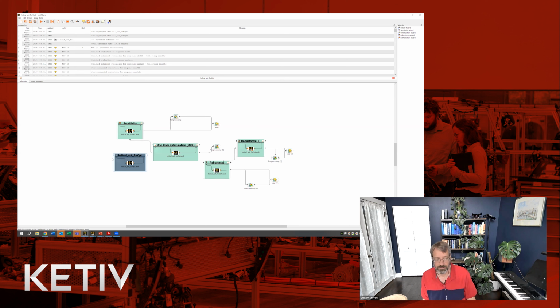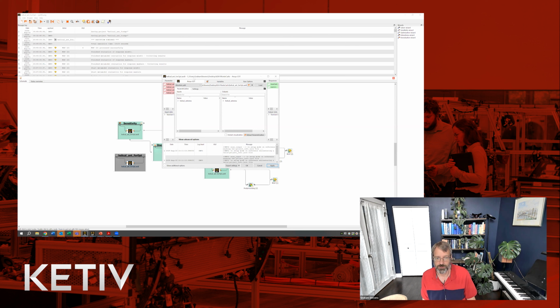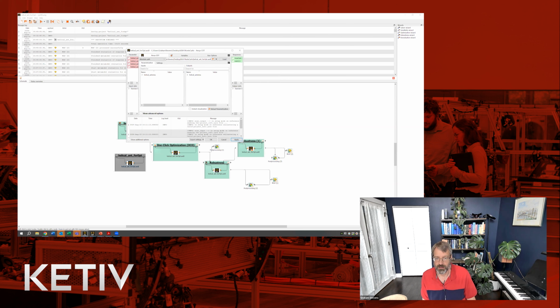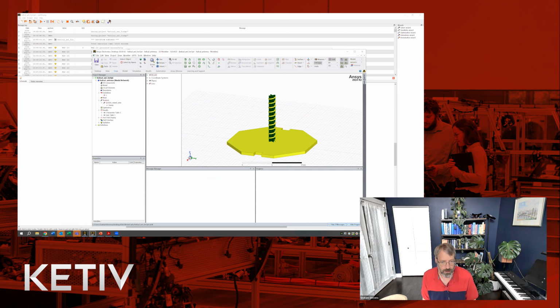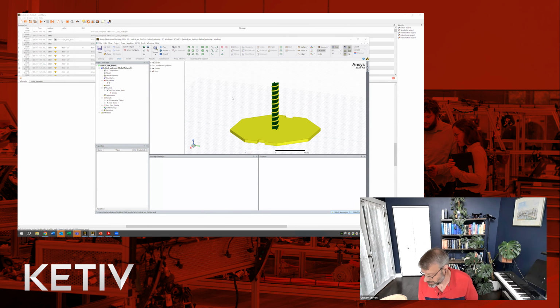And typically within the solver wizard, you'll also set up this link between AEDT and Optislang, where you have an AEDT model that's indicated here. This is where the model is, and then what the outputs are. And typically when we have this model, so I have this helical antenna for optimization for Optislang here, it's important to reduce the model's computation size and length as much as possible.